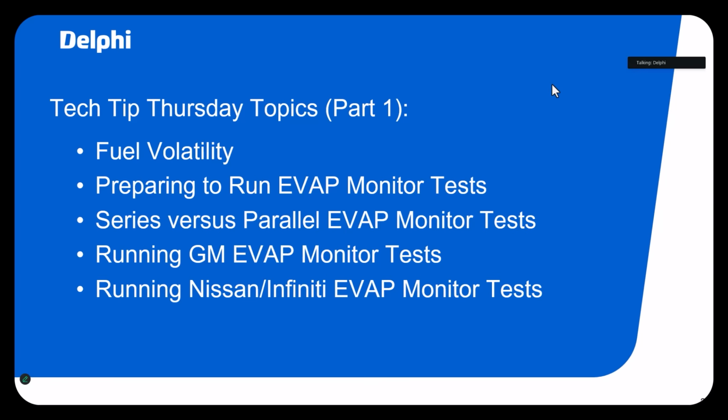But just in good practice, we want to run EVAP monitor tests if we can to verify or repair. Just that in itself is worth doing it. And so many times I've heard people say, oh, they don't run. I know depending on the part of the country you're in, there's times of the year where certain EVAP monitor tests will not run because the environment, the temperature, just is too extreme for EVAP to run. But now that we've gone to the key-off systems and the pump systems, the frequency with which they run is much better than it used to be.